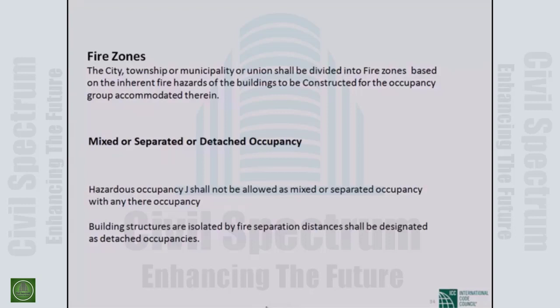So you can ask the question, detached means how far? It may be 1 foot, it may be 3 feet, but it is detached. There will be some gap, or sometimes there will be no gap, just a very thick wall. Then it is detached, totally separated. In BNBC, there is no definite table about detached buildings. So I will show you a table from the IBC, which will give you a detailed idea of how detached buildings are made. I will come back to this.